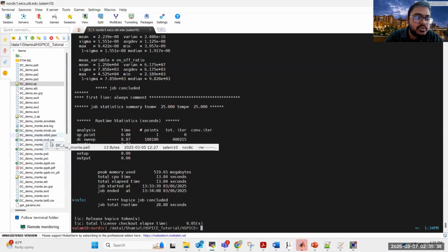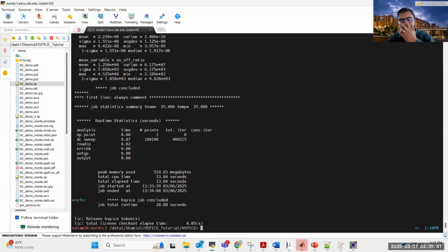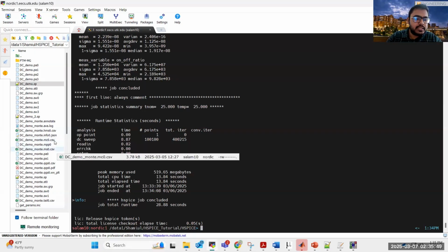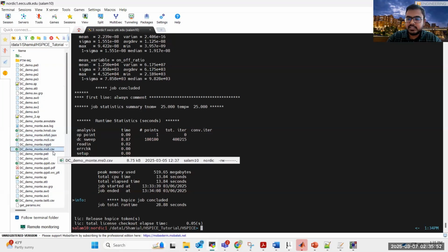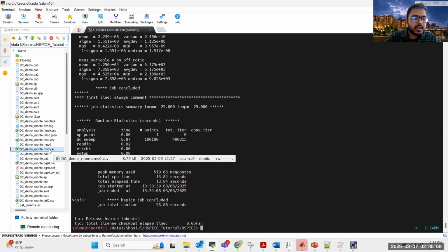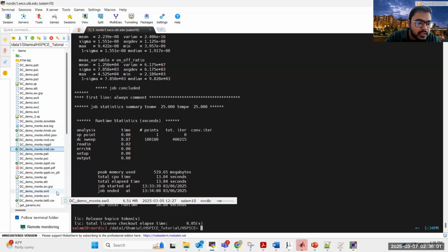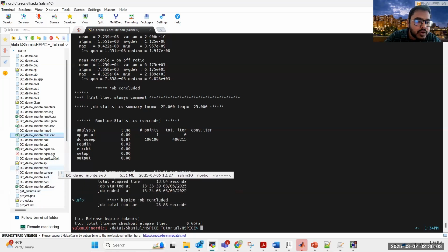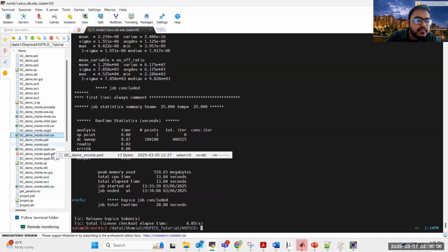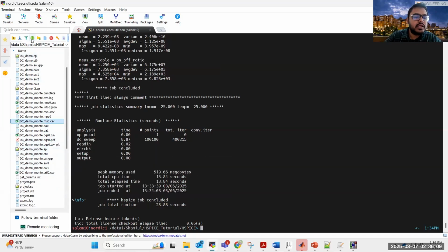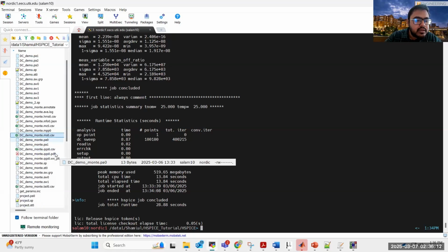And again, since we have the measurement results, if we go back to the terminal, since these are DC files and we used meas form equal 3, if you remember, it should give you the Excel format. So we should have two Excel files. You see the first one is ms0, since this is DC, so this will be ms. If you are doing transient, this would be mt0. So this is one ms0.csv, and you should have another one called ms1.csv. I think you have to refresh this. Yeah, you see these output files.